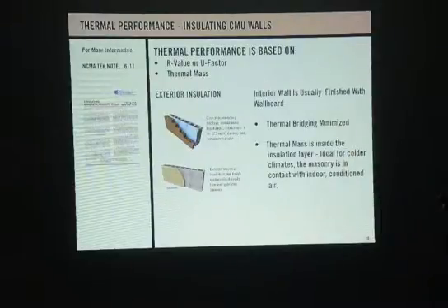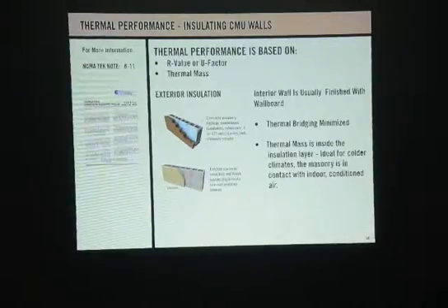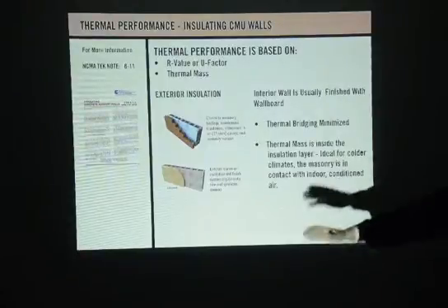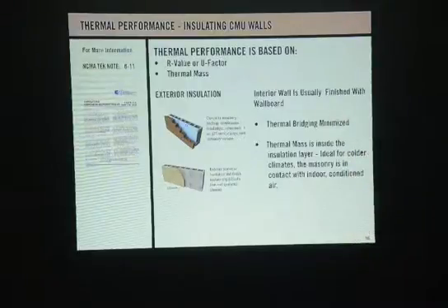But there they had a double open end, and there weren't 3 webs, there was only 1 web. So that means less potential problems with thermal bridging, because the entire area is better covered. We don't have spaces that could be susceptible in a protected area where there's block by having more than one.